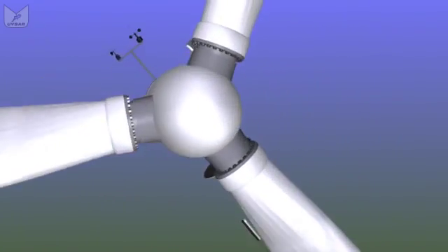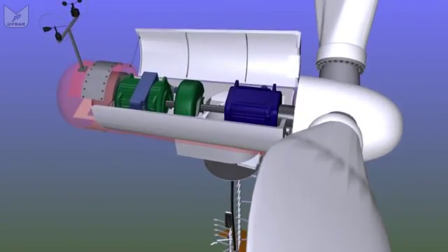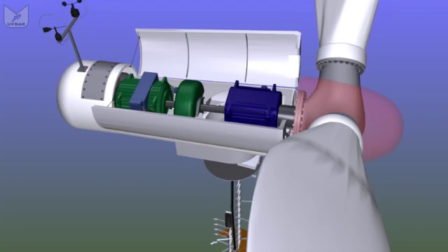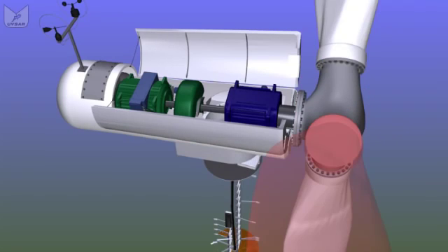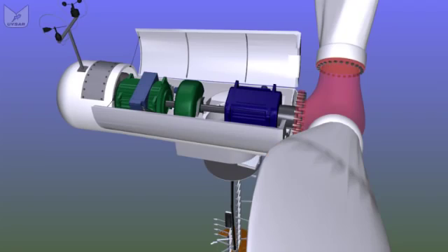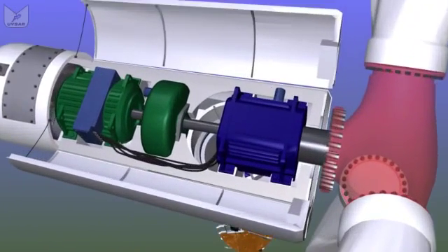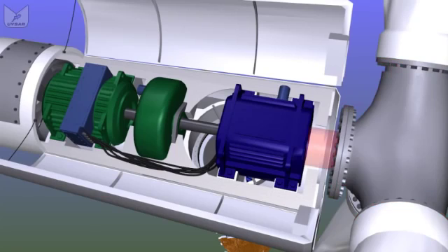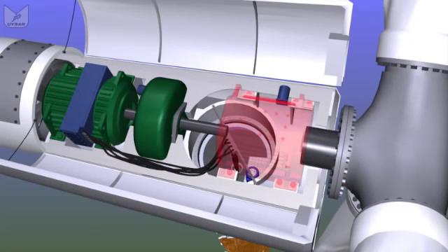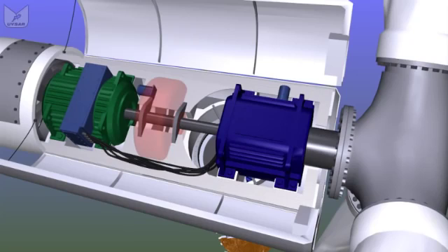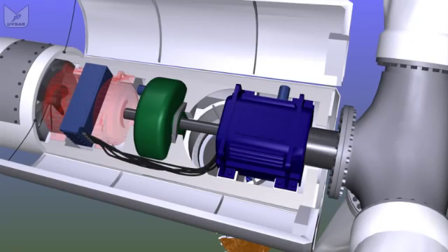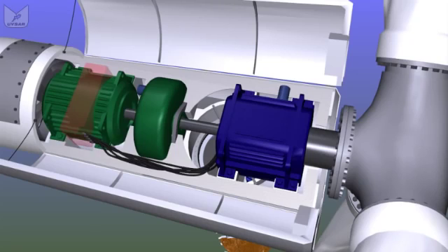At the front we have a similar fiberglass cowl protecting the hub, which is a steel casting on which we have bolted our three blades, and the blades can turn or pitch so that the angle they form with the wind can be varied. Out of the back of the hub we have a shaft which leads into the gearbox, then a high-speed shaft through a brake into a generator, and that generator then supplies the electrical power, as I say, at about 690 volts all the way back down the tower to the base.